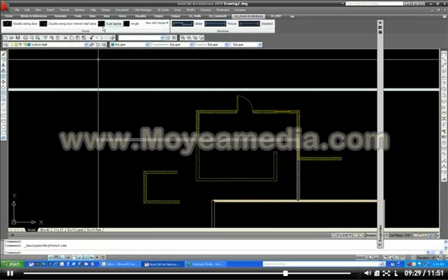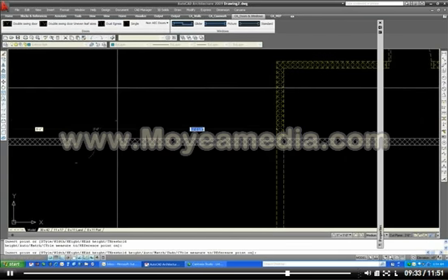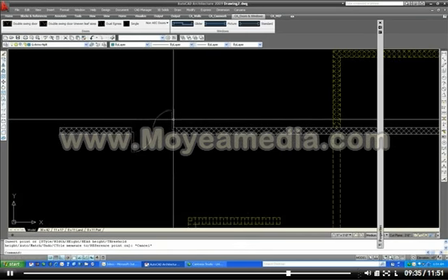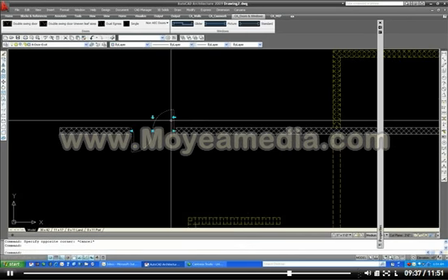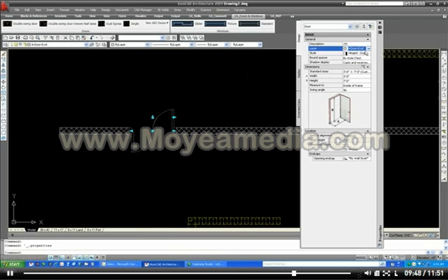And now this time I'm going to go with some dual egress doors right here, and I'm just going to select this wall. And as you can see, this door is on the correct style, the door double swing egress. Well, actually the hinge dual egress style, but look over here at the layer style. The layer style came out on the correct layer because it's an existing door and existing wall, and it came in on the correct layer.